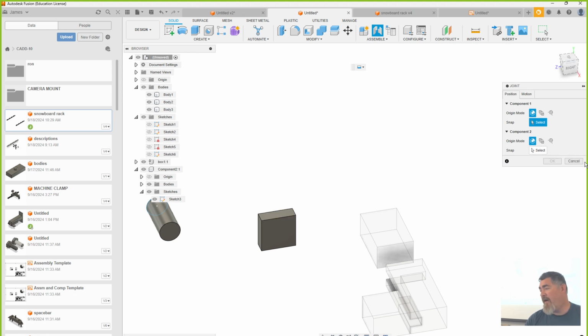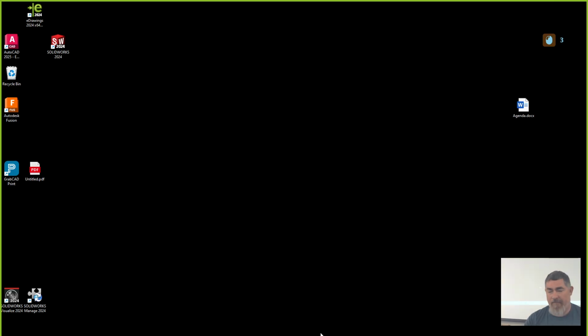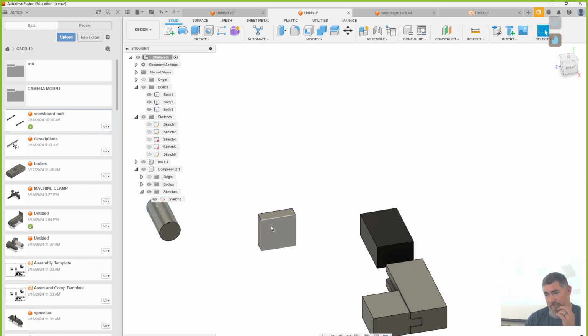All right, so work on the bodies and components activity now. Yep, what, Steven? With the edges, yep. You have to click access before clicking on the edge, or just when you're doing the joint, if you're on the edge anywhere, it's going to be perpendicular to that edge.